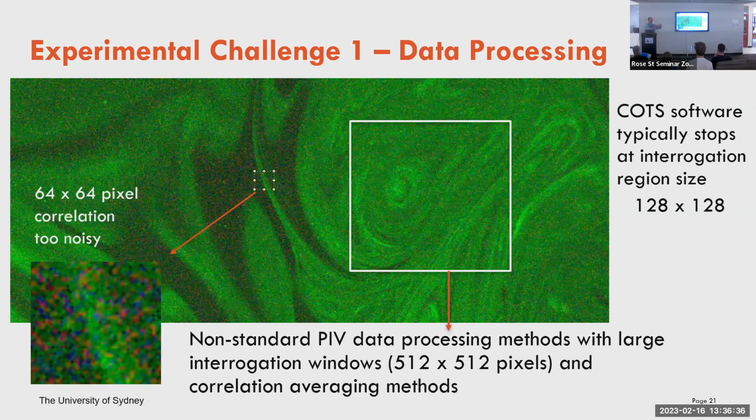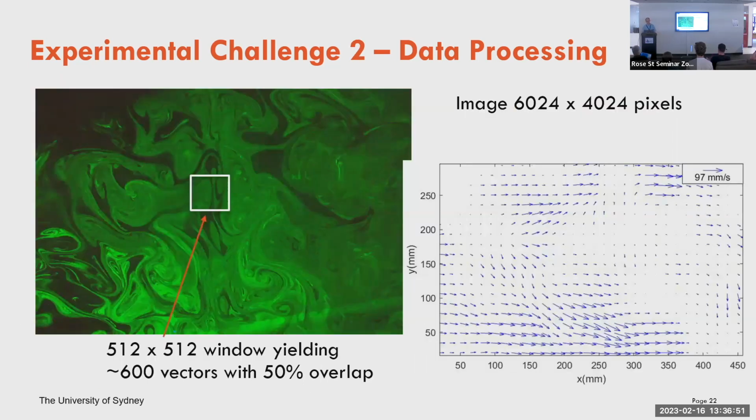Eventually the smoke all mixes up and you can't see a distinct pattern anymore. So you then have to flush all the smoke out, put the fans on, and then put the smoke in again, let the pattern develop, and then do the correlation based on that. We were looking at quite large areas in the big image anyway, like a 25 megapixel image. We took these larger areas and then tracked these patterns, and it worked quite well. We got some basic data.